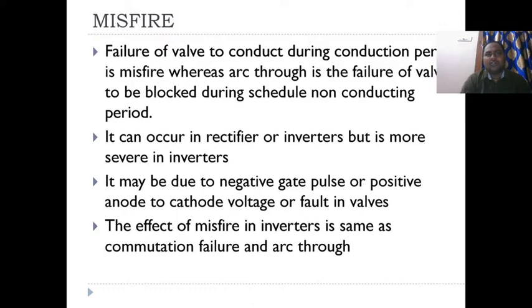The failure of a valve to conduct during the conduction period is a misfire. Misfire means the valve is not fired at the exact firing angle. The angle will be deviated. The firing angle or extinction angle gamma is deviated. This causes a lot of change in the output waveforms, and the output does not occur properly.